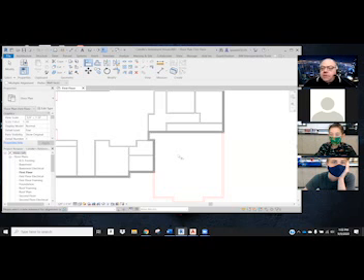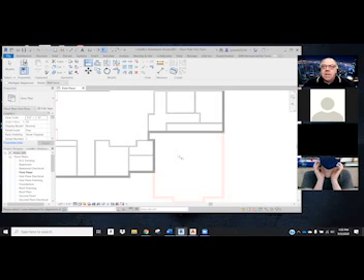And the separation wall is only used in the garage. Now, some building codes require that you put around a stairway. You also need to put 5/8 inch gypboard on the stairway. What we will do with the stairs when we do the walls there, we're going to put 2 layers of 1/2 inch. So it's going to be a little different situation, and we won't do those walls until we do our stairs. We want the stairs to be the very last thing in the house that ever burns. So we put an extra layer of safety there.